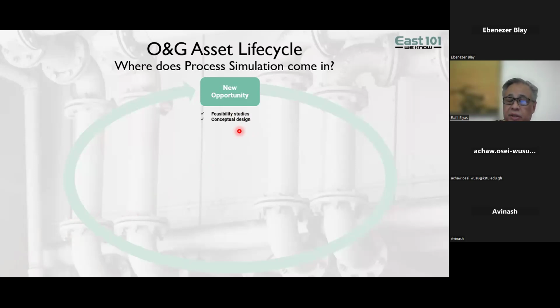For example, if you're taking a look at an upstream facility where you've got an oil production facility, one of the things that you're going to encounter is multi-phase flow. You're going to get liquids and gases coming in through pipelines, coming into separators. So you need to take a look at things like slug catchers for your front end. You might have a compression system. So you'd be thinking about compression systems, gas lift, fuel gas systems, things to do with your gas. You probably need to dehydrate them, etc.